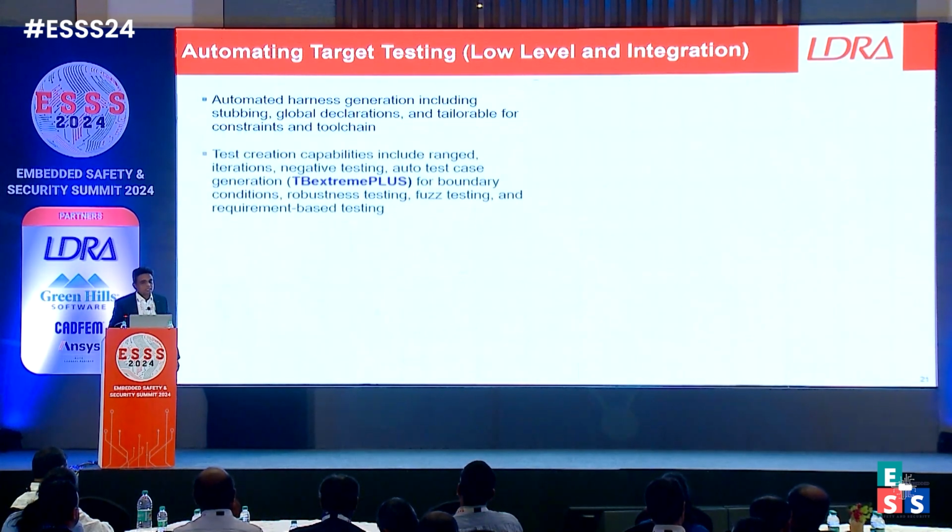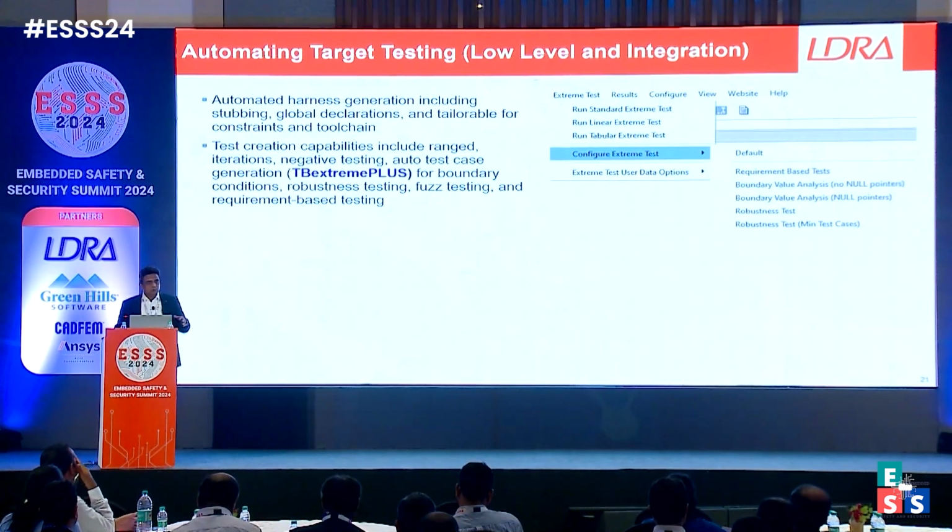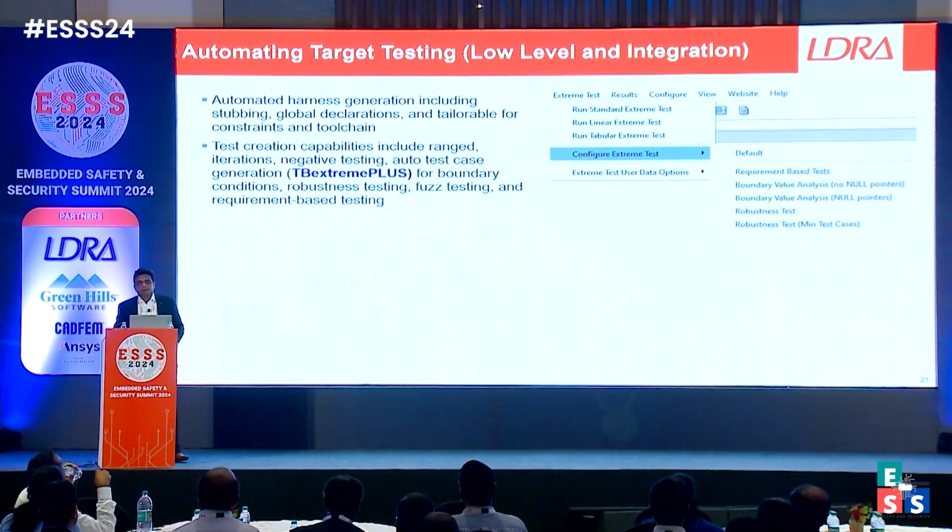But we have enhanced it to a different level, where we have the TBextremePLUS, where we can automatically generate the test case and we can populate the input conditions automatically, where the user can create user profiles, and in the user profile you can define what is the criteria under which the input needs to be populated. For example, I can provide min, mid and max values. If I enable the min, mid and max values for a particular configuration, and if I run the Extreme Plus, it can automatically generate that many number of test cases for the min, mid and max value.